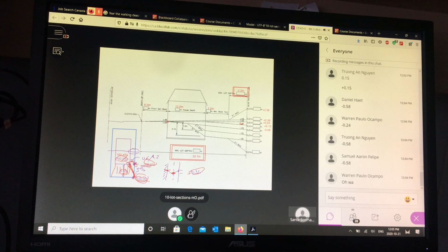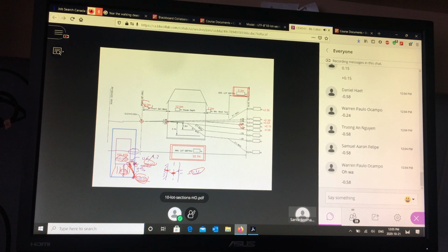So start at the front, 0 elevation. Go 8 meters at 2%, whatever that number is, and then subtract 3% of 12 plus 7.5 plus 5.2. So 2% of 8 gives you the elevation at the front of the building. And then from the front of the building, you're going to go all the way down to the backyard at 3%. So 12 plus 7.5 plus 5.2. Yeah, exactly. Okay. So there we are.